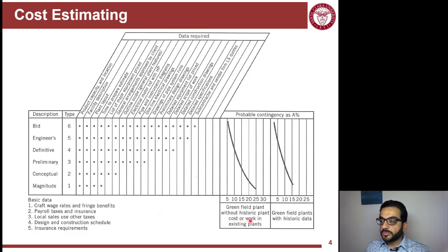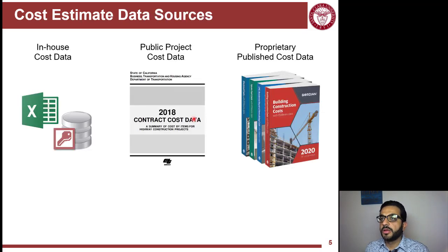But also it's about hidden conditions that you're not aware of. So brownfield projects, or what we call existing plants, renovation projects, have a lot of risks in them. You don't know what's inside the wall, and how the building was built before. So contingency here is just a language to refer to your risk. What's the risk that you need to include in your estimate?